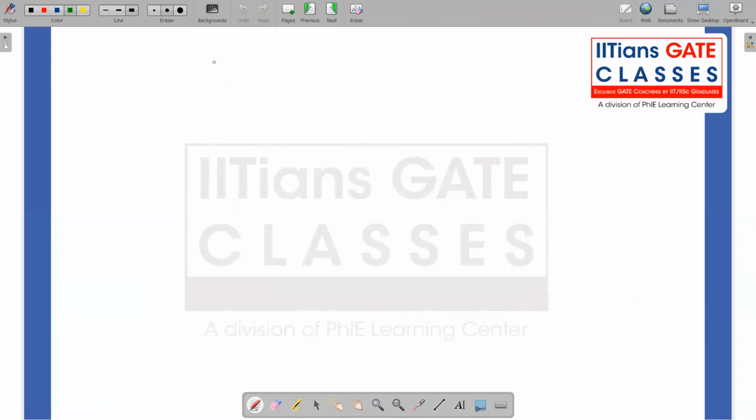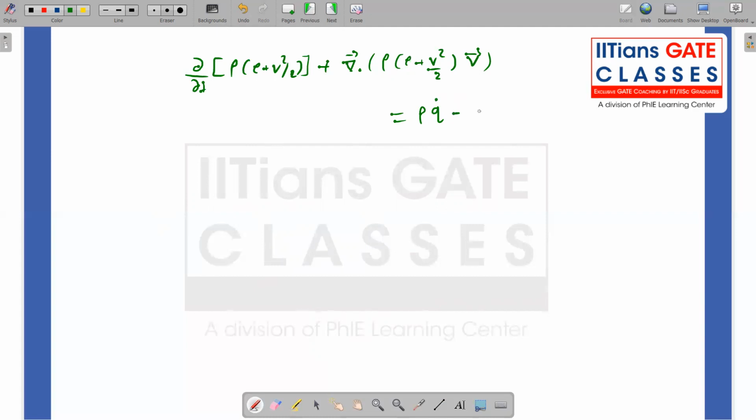That leaves me ∂/∂t of rho times (E plus V square by 2), plus the divergence of rho (E plus V square by 2) times the velocity vector, equal to rho q dot, minus the divergence of pressure times velocity, plus rho times f dot the velocity vector. This is my energy equation in differential form.